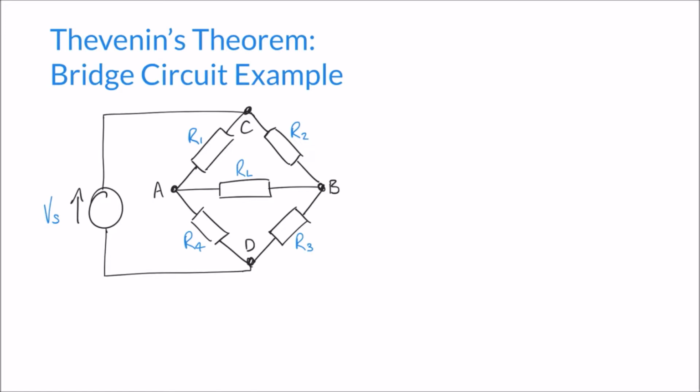And so in this particular example we're going to look at another bridge circuit. This is an example more commonly known as a Wheatstone Bridge, which is this diamond arrangement of resistors. And Wheatstone bridges are often used for a variety of different purposes, but largely to determine the values of unknown components. What can be done is, let's say one of our resistors here is an unknown value. We've picked a component that we don't know the resistance of. Let's say it's this resistor R3 here.